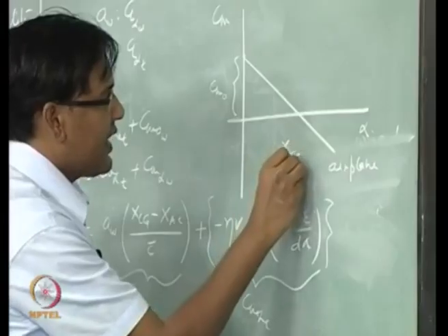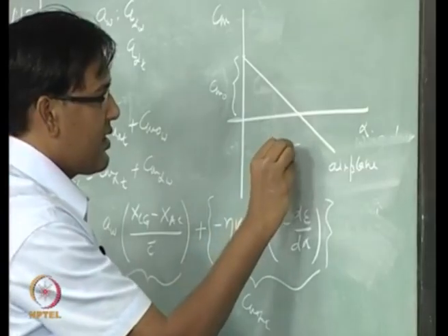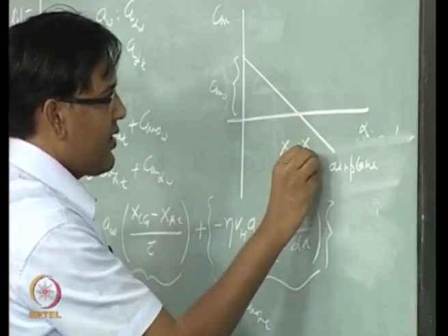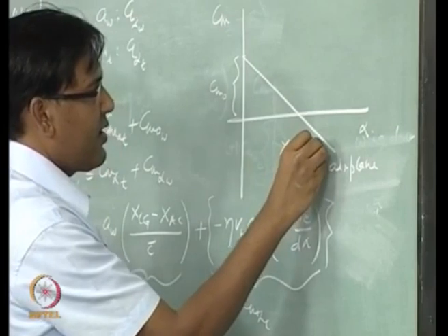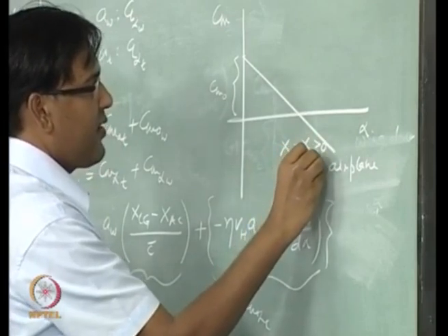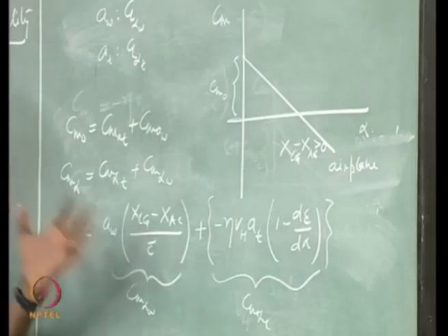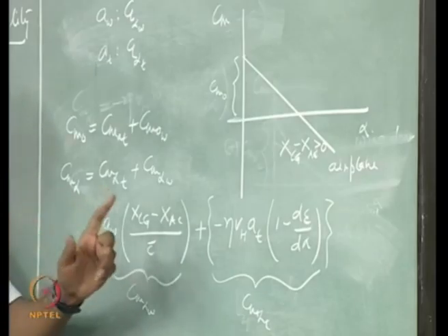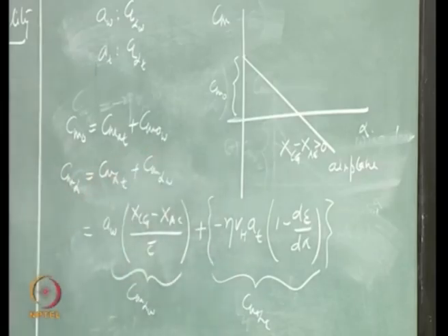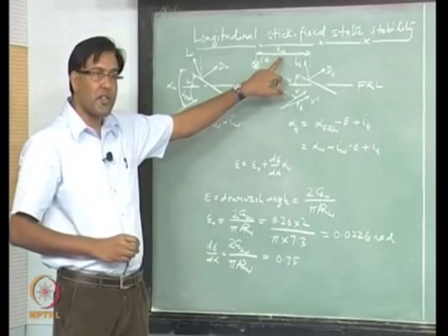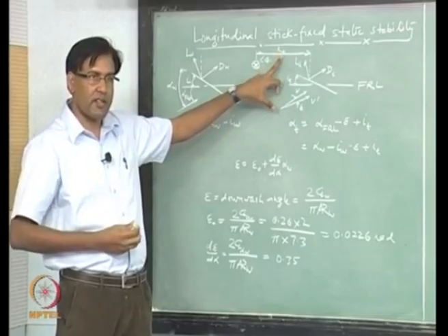So I can say that, right. Now let us start moving this CG. CG is of course going to have an effect also on the tail arm length, right. This LT is also going to change if you start changing the CG, right.